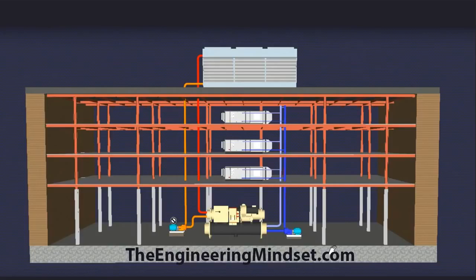I'm pretty pleased that some of you have spotted that this pump here is actually piped around the wrong way. This pump should actually be connected to the riser here, or the flow pipe going up to the cooling tower of the condenser water system. Unfortunately I made a mistake when I was rushing to put this video together, and I piped it onto here, but thank you for pointing that correction out.